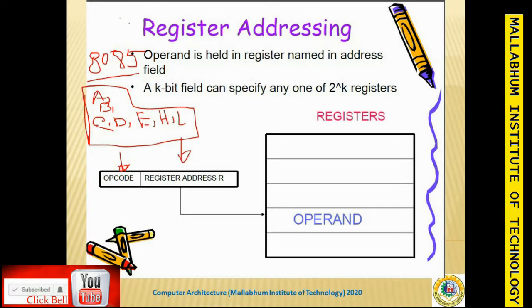In this type of addressing mode, the operand is, rather than immediate data or an address, directly the register. In a long program execution where we want to store the intermediate result in a register, accessing the data is much faster than storing it in memory, because accessing data in memory is much slower. That's why we store the result in an intermediate register where we can access the data much faster.